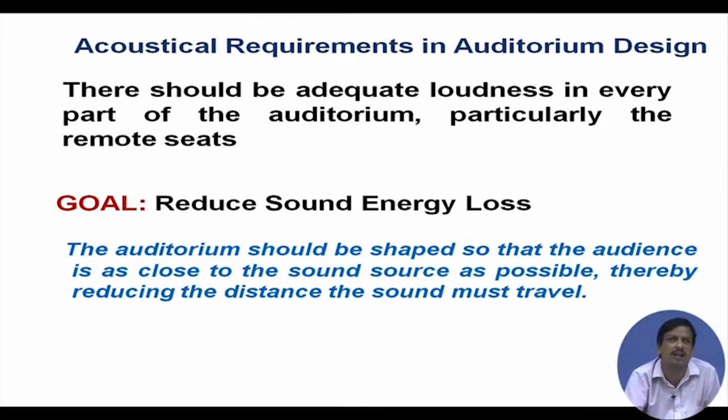The goal is that we should not waste the sound energy. So, reducing sound energy loss, how we can channelize the sound or distribute the sound inside the whole auditorium is our goal. The auditorium should be shaped so that the audience is as close to the sound source as possible, thereby reducing the distance the sound must travel.